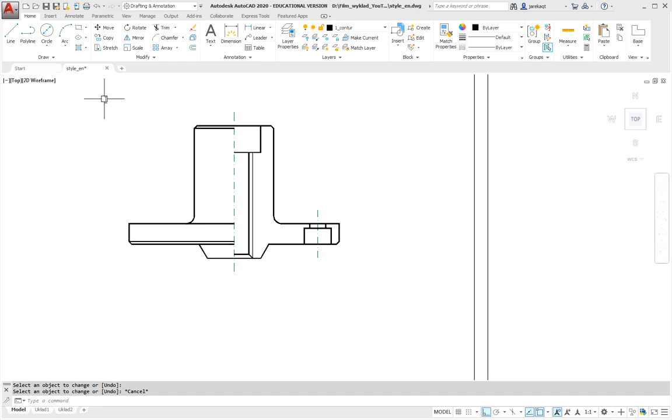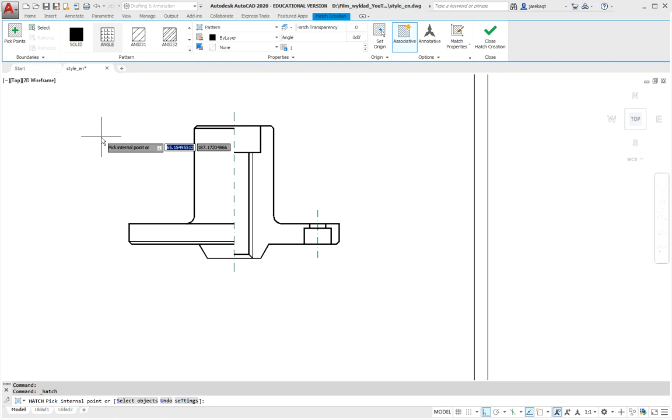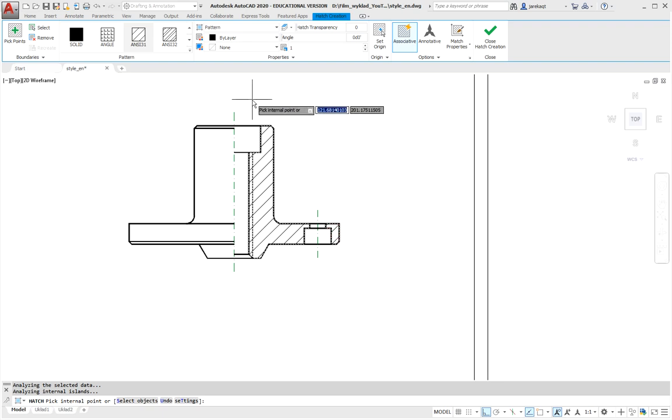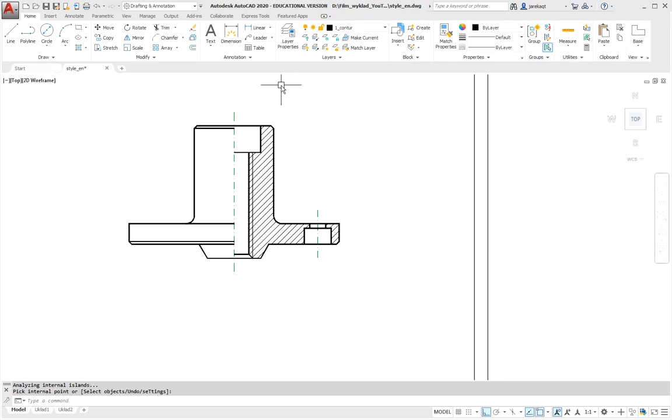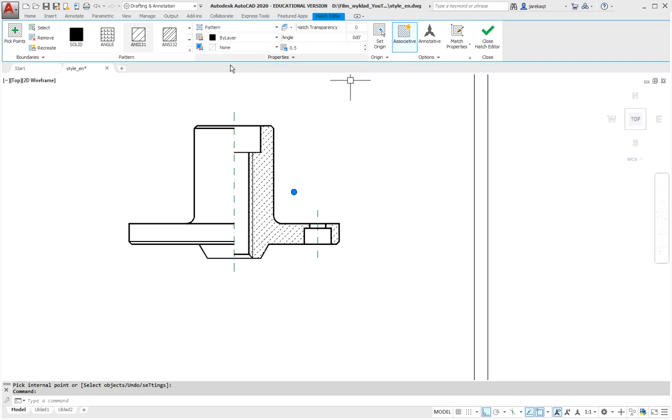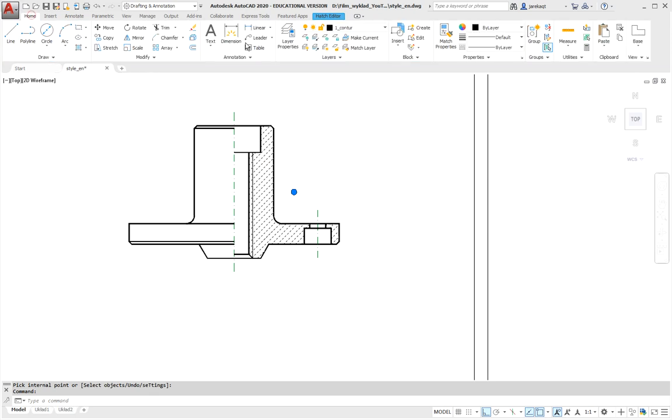Of course, so that it was a correct entry, we still need to add a hatch here, so that we choose, because it is metal, we choose ANSI 31. We check the boxes, and because here it is a bit too rare, let's assume that it will be 0.5, you can choose some other factor. And again we could change the layer first and then draw, but change the layer to draw one element.